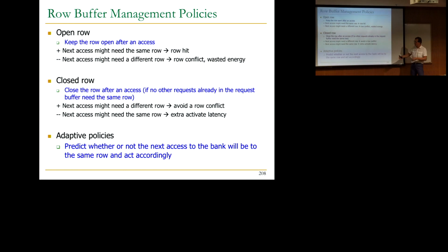Actually, there's wasted energy because of this also, the extra activate latency. I should have put, for parallelism purposes, there should be wasted energy over here as well, yes. But in this case, I think I emphasize it because you may not think about an open row wasting energy, but an open, activated row actually wastes energy. And that's actually a problem in these sort of devices. So some of these devices aggressively close the row after some time.